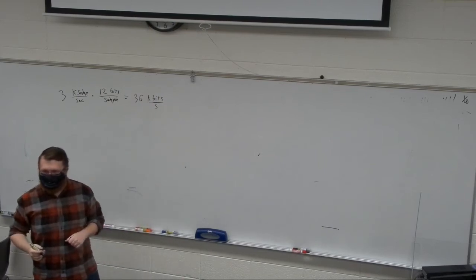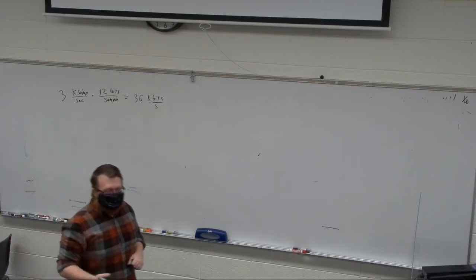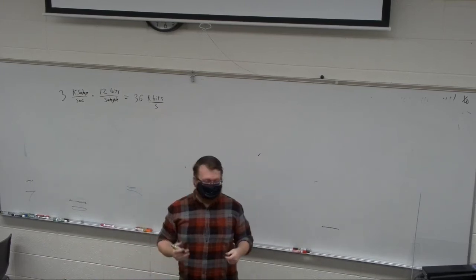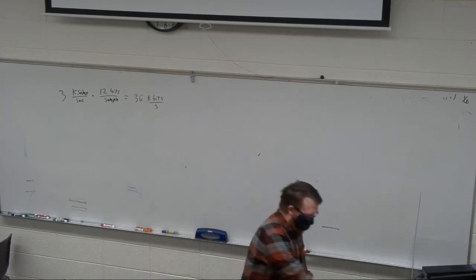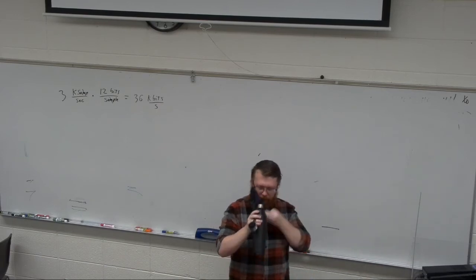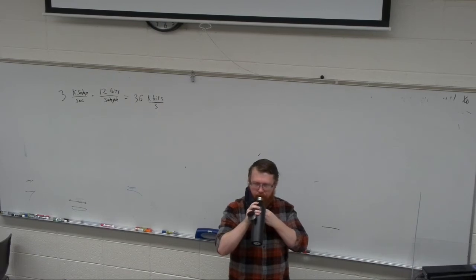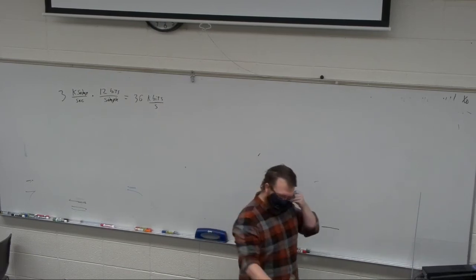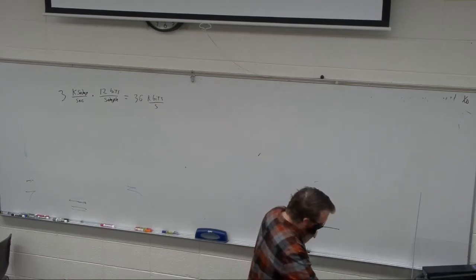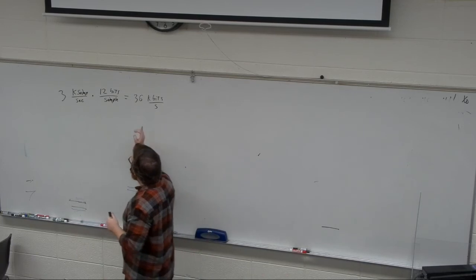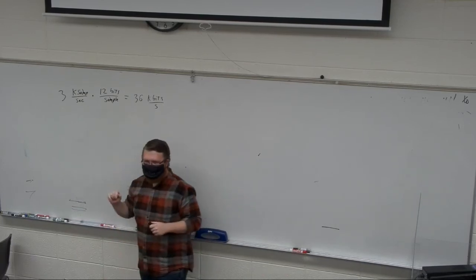Now, when I convert this to the UART, my UART has 8 bits. So I can't fit all 12 bits in one packet.